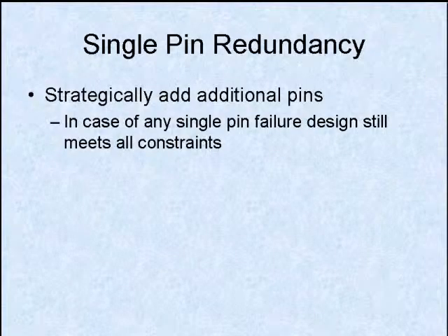The goal of single pin redundancy is to ensure that the power grid can still meet its constraints, even if there is a failure of any single pin. First, we find which pins need to be redundant, and then we find potential pin locations that can fulfill that redundancy. We formulate this problem as an integer linear problem and solve it using GLPK.